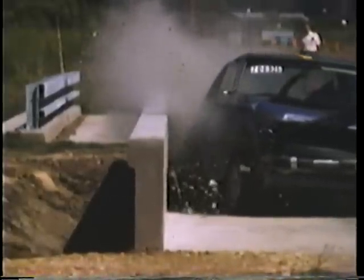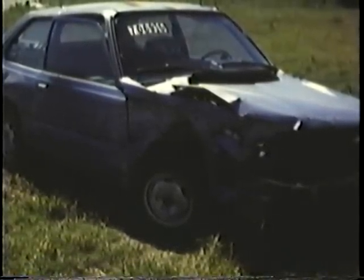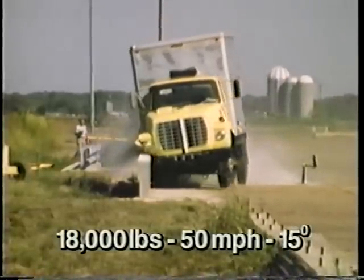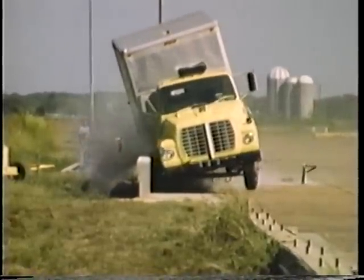Unfortunately, the wheels are frequently damaged, and this can cause the post-impact trajectory to be unpredictable. Unlike the safety shapes, a collision with a vertical wall almost always causes damage to the vehicle. Since the vertical wall has no sloped face, the energy of the crash must be dissipated through damaging the vehicle. Although the vehicle and its occupants experience greater forces during the impact, the chance of rolling the vehicle over is significantly reduced. In the single-unit truck test, the vehicle only rolled 18 degrees, much less than either the New Jersey or F-shaped barrier tests. The vehicle was more stable in this test than in previous heavy vehicle tests.